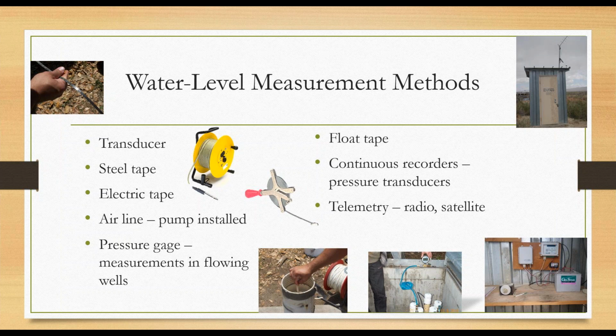You can get that if you have a weight at the bottom of a tape, it's possible to get that stuck in a well, on a lip of a well where maybe two pieces of casing are joined together, and that could break away and cause some problems. But so that's kind of some downsides of the electric tape. The steel tape. The electric tape is also used quite a bit by USGS.